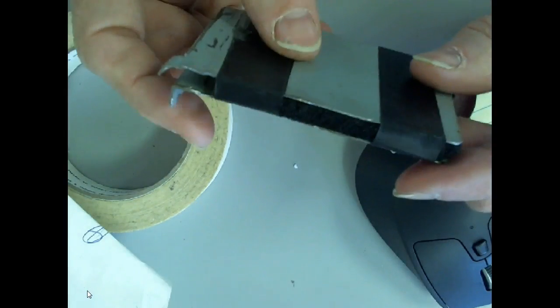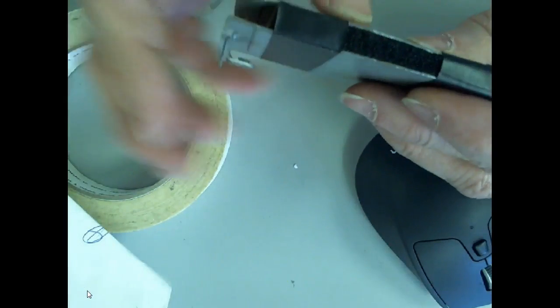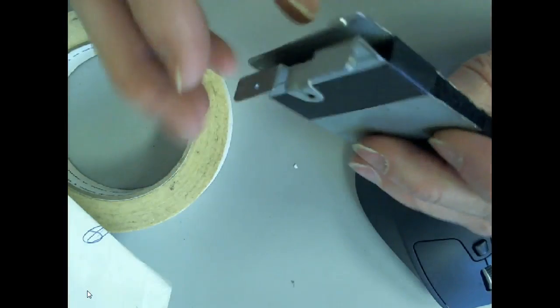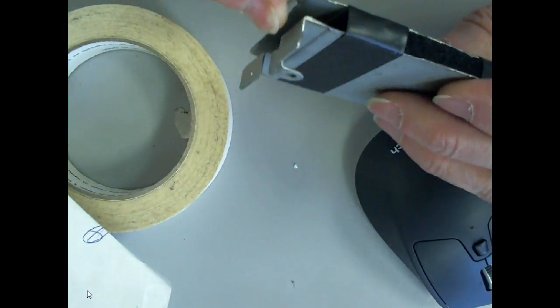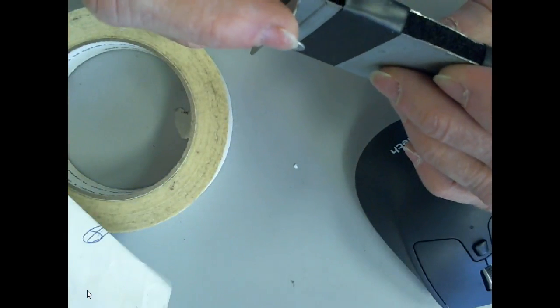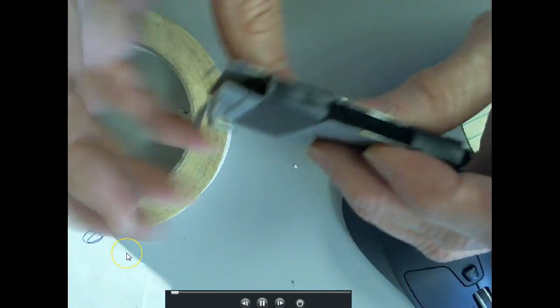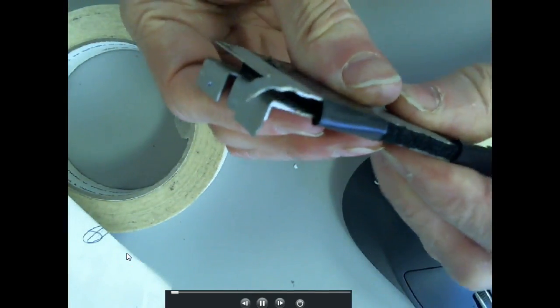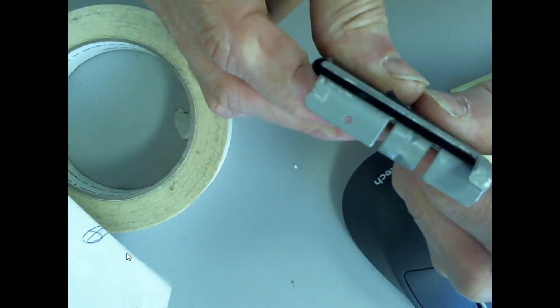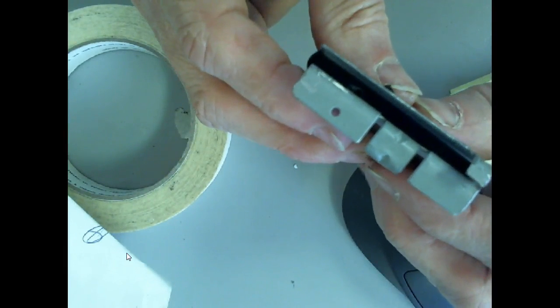This is what I made. So we have two metal plates, and in between we have this carbon impregnated foam. And I've got two metal tabs here, so you can hook your meter up to this guy and hook it up just to this metal right here. And then all you have to do is just compress it. And you'll see when you compress it, the resistance is going to do what? It's going to go down, and when you uncompress it, the resistance is going to go up. Since Kareem got his meter out.